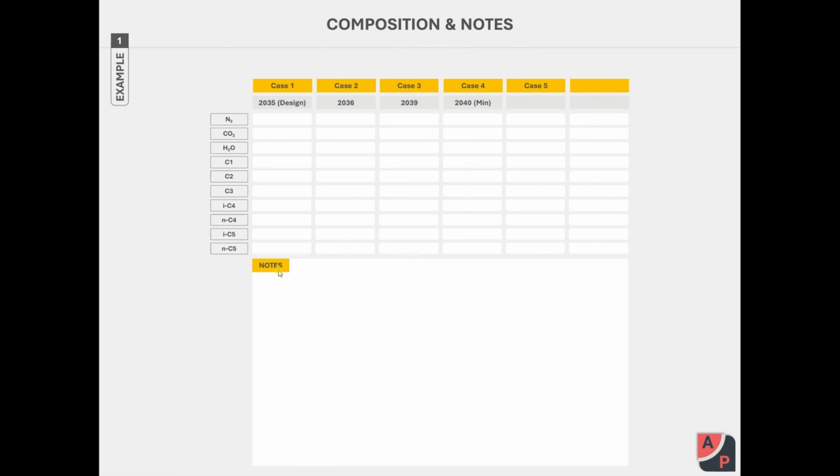Another thing is adding the limitations. In the previous session, you remember we had a discharge temperature limitation of 135 degrees centigrade, and we considered a 5-degree margin, so 130 degrees centigrade is the limit for the design of the compressor based on our given design cases. Now an exercise that demonstrates how to map operating cases and locate the process data required for a compressor process datasheet using our examples.